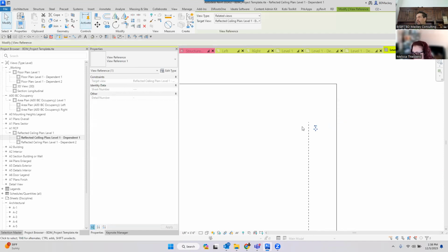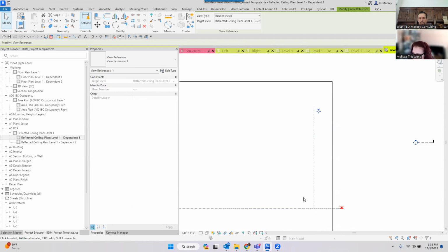The one client I had, they were on 36 by 48 sheets for the Miami Beach Convention Center. And I think they had 48 sector plans to get that on at 1/8 inch scale. So all 48 sector plans, every single corner of every single match line, took the one person like a day to do. Using apply dependent views, boom, it sets them all up.